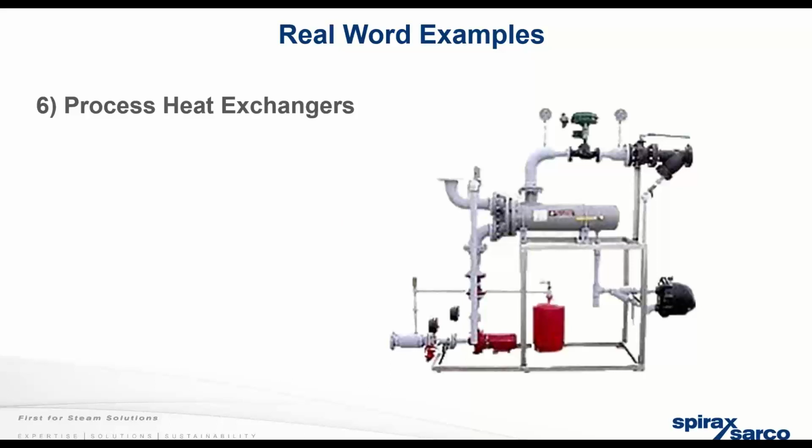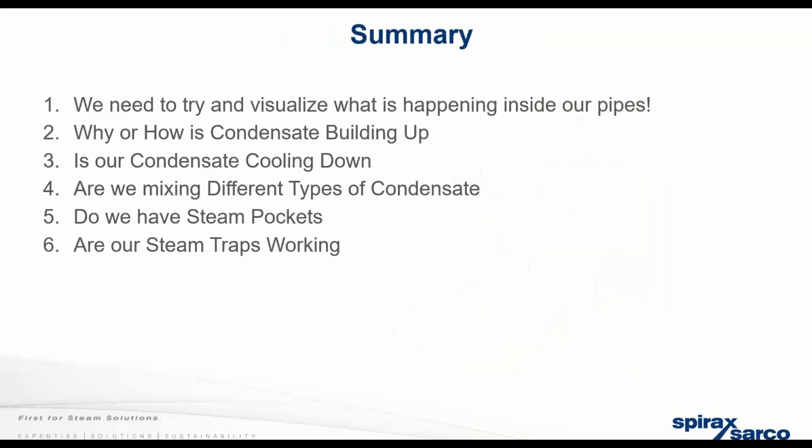It's not really water hammer. What it is called is localized boiling. So localized boiling is a huge problem in a no flow, low pressure situation, and it just basically takes out the steam trap. Might take out your heat exchanger, so it could be very expensive. So something to be thinking about, looking at, maintaining a process temperature higher than your steam pressure.